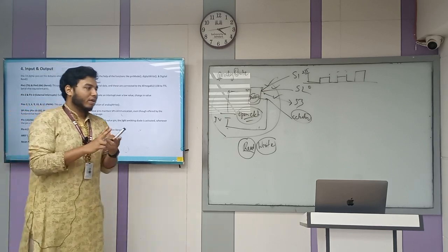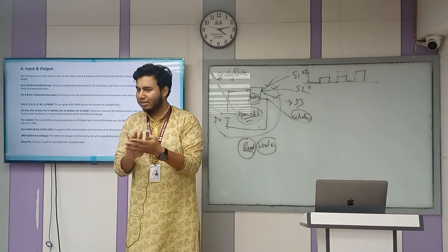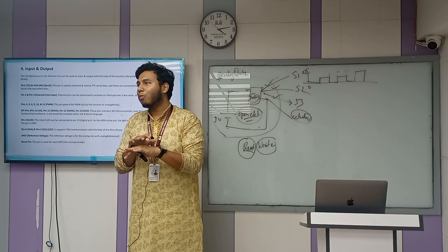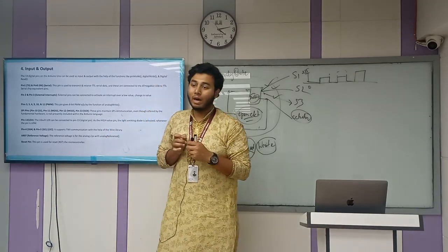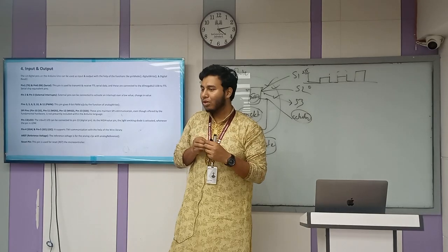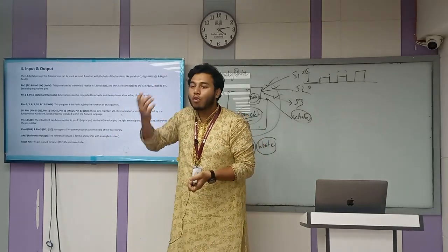Say you have an LED, you have a motor, and you have an LCD display. I think you can't operate smoothly with the Arduino. Why? Because your pin numbers are limited. All the pins will be filled up by the LCD display, because it needs more wires.